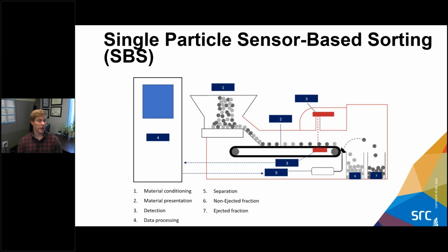Depending on the technology, like XRT, for example, it can see through a thin layer of mud on the top. But with something like laser, where you're trying to penetrate through a transparent technology, you need to have that clean. So there's cleaning. There's also moisture, depending if you're using a belt or a chute or if it's water fed. You could have caking in the machine, which can cause actual mechanical issues.